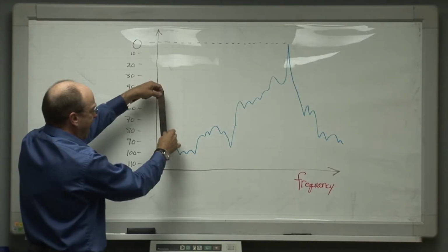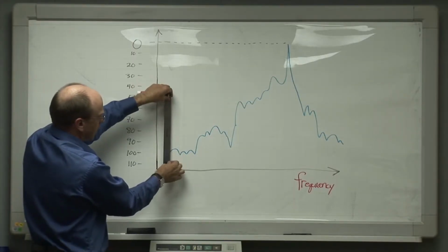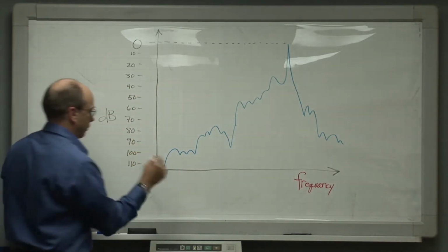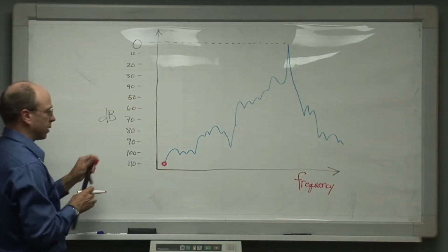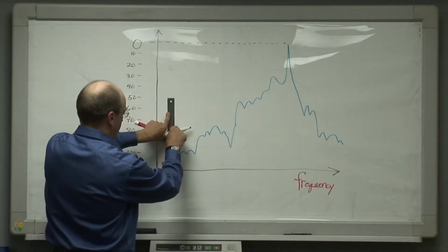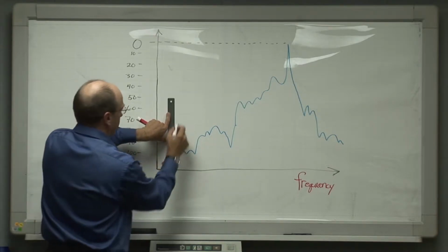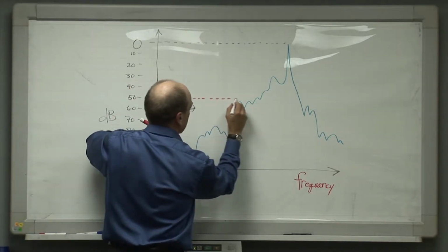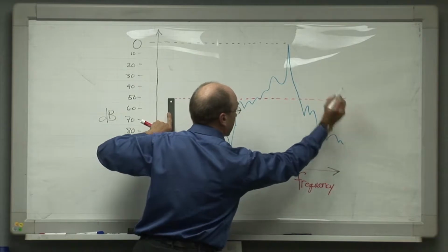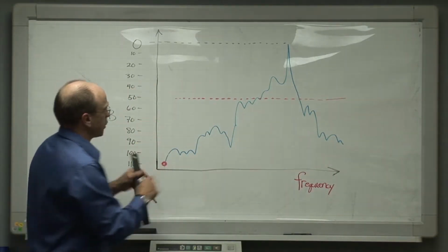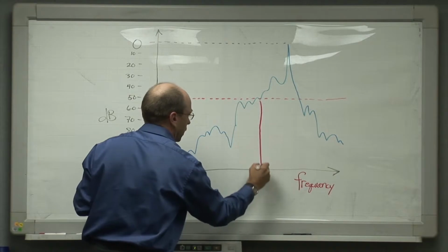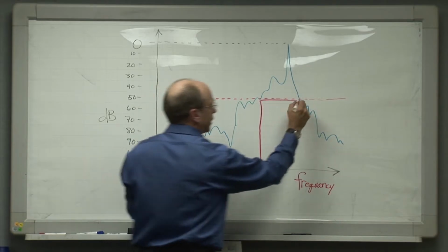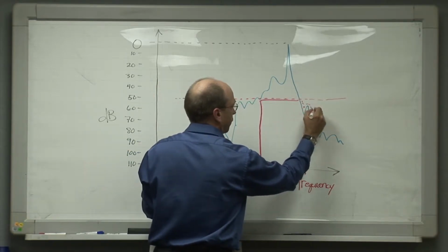Well, we can do that if we could get enough sensitivity at the front end of the spectrum analyzer to see this signal right in here at that point, that we could then measure the emissions in this radar spectrum until we hit this level right here. And if we tried to do that, we'd be able to measure this part of the spectrum up to this point, and then beyond that point we would start to limit or saturate on our measurement, and then when we got to this point we'd start to be able to measure the spectrum again, obviously.